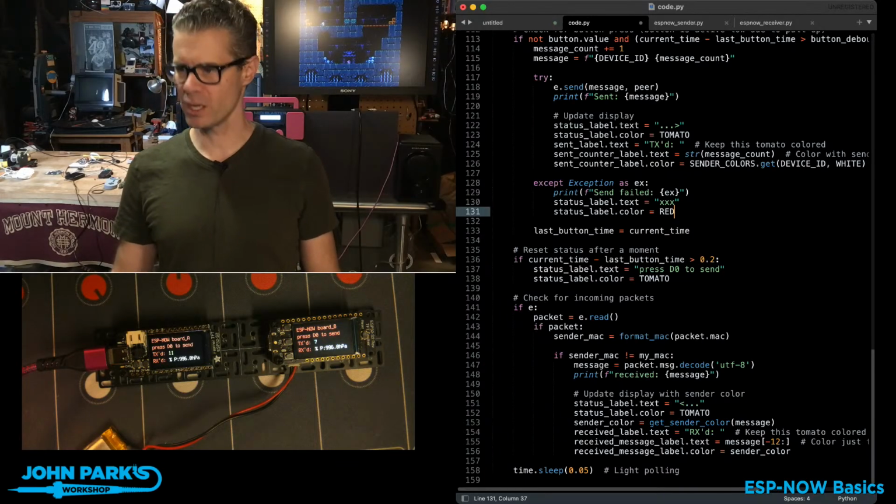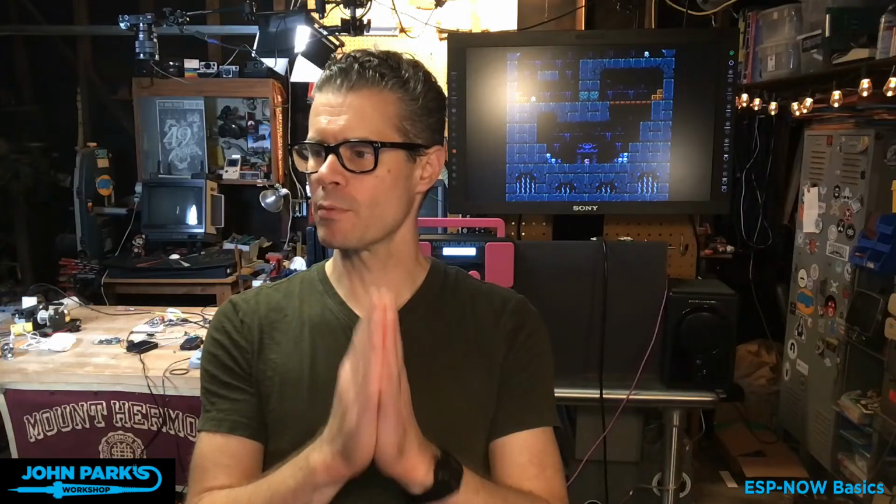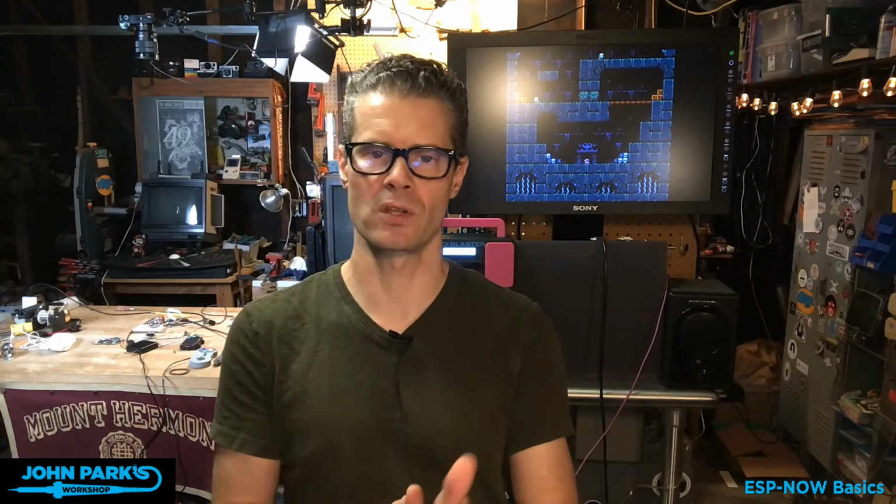Foamy Guy says, the chip is capable of it. So this is back to the question of, do we think we'll have ESP-NOW available on the Fruit Jam? Chip is capable, but I think it will depend on whether Nina firmware and ESP32 SPI libraries have support for ESP-NOW to work in CircuitPython on the Fruit Jam. Yeah, okay, so there are things I don't know about that either, so we'll wait and see. Chip can, but will the rest of it support that? Not sure.